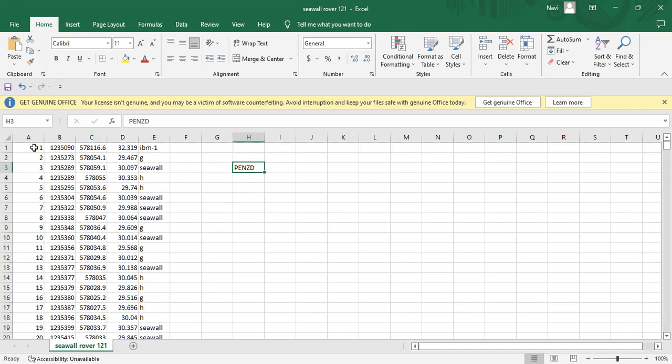When you organize your data according to this format, it can be P N E Z, it can be P E N Z, it doesn't matter, but you must know your format. If you use northing and easting the opposite way, then when you import your data, it will import, but it will not be correct.